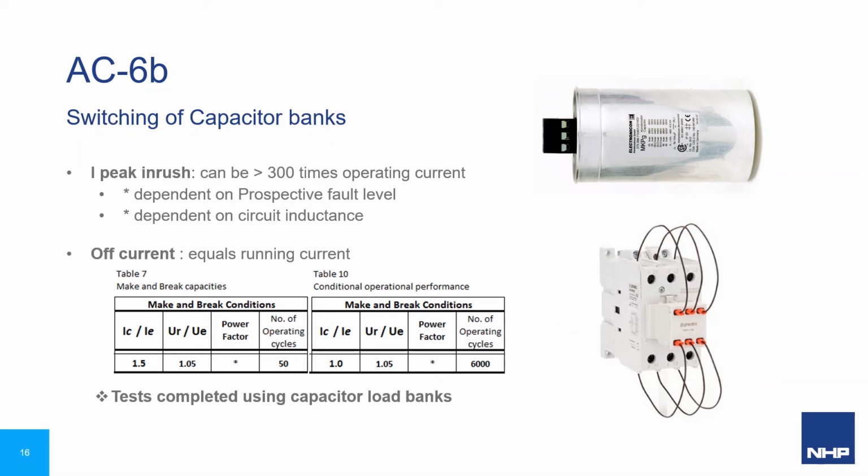In power factor correction systems, a standard contactor would need to be greatly derated from its AC3 value to cope with the very high inrush currents. So inductors are included as part of the design, and contactor versions for capacitor switching are designed to include early make auxiliary contacts, which insert resistances into the circuit to pre-charge the capacitors before the main poles are closed to reduce the inrush peak seen.